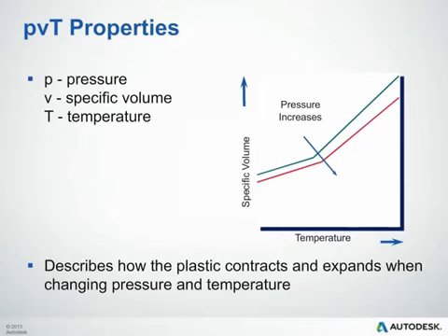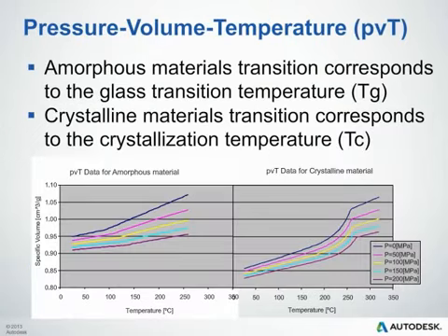Very important relationship to capture. The PVT diagram also gives us the opportunity to capture a unique transition that happens in amorphous and crystalline or semi-crystalline materials. So with amorphous materials, this transition corresponds to the glass transition temperature.